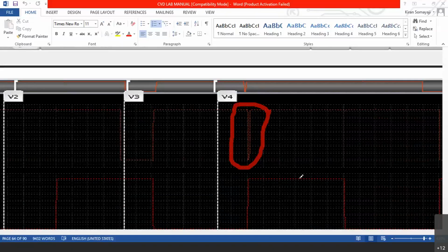Now this waveform has got a particular name. What is it? Anybody? There is a particular name for this waveform. It is not occurring because of the levels, it is occurring because of the edges, because of the rise time and fall time, which are finite. So such waveform is called glitch. Remember this? This is called glitch, which is an unwanted waveform.